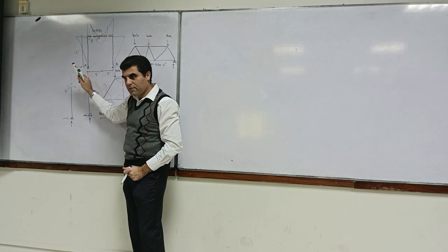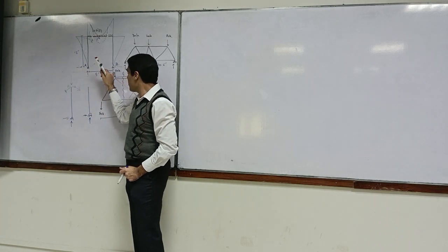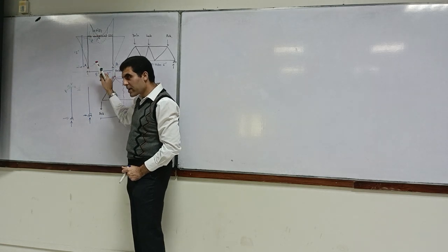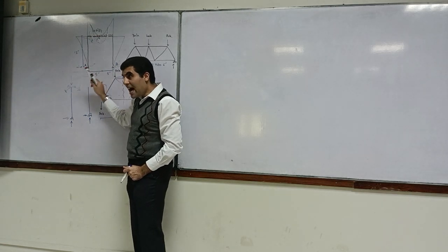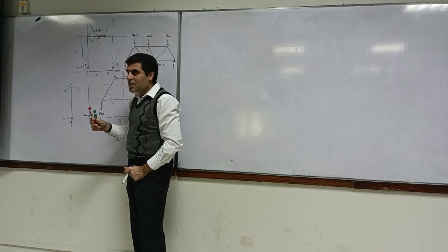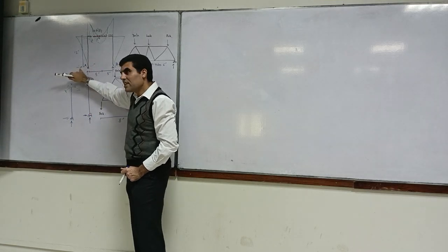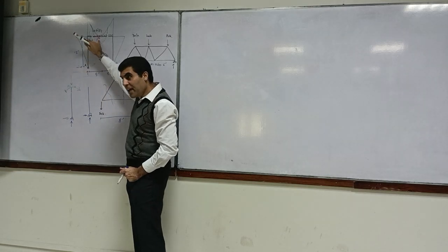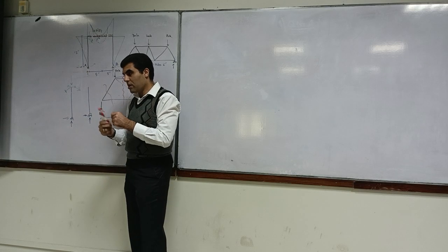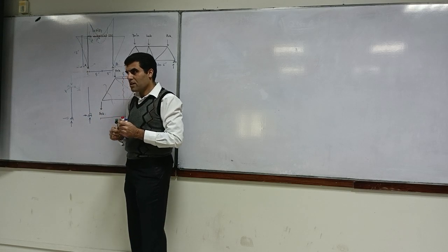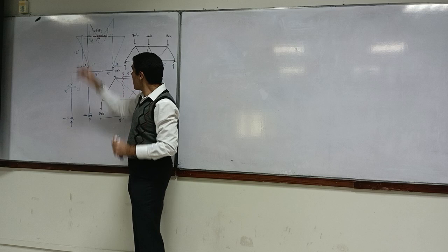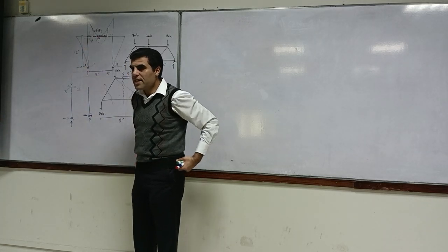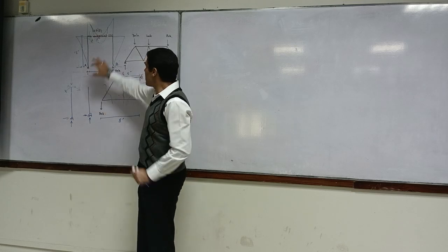You can find out the vertical from here. Summation of Fy will give you the vertical over here, or either you can do the same thing, summation of moment about this point equal to 0 and you can find out your verticals. Now you have the verticals. How would you find out this horizontal? Because we have got a third equation which is over here. Then you can find out your horizontal. Taking moment about both points and checking both. Yes, this gives you an additional equation for moment. Do you understand my point? Yes, sir.